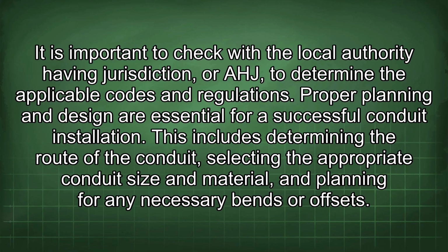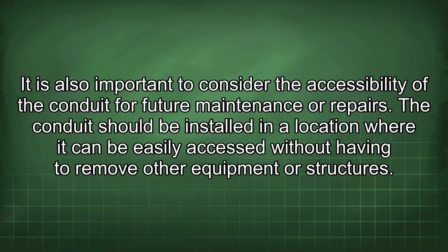Proper planning and design are essential for successful conduit installation. This includes determining the route of the conduit, selecting the appropriate conduit size and material, and planning for any necessary bends or offsets. It is also important to consider the accessibility of the conduit for future maintenance or repairs. The conduit should be installed in a location where it can be easily accessed without having to remove other equipment